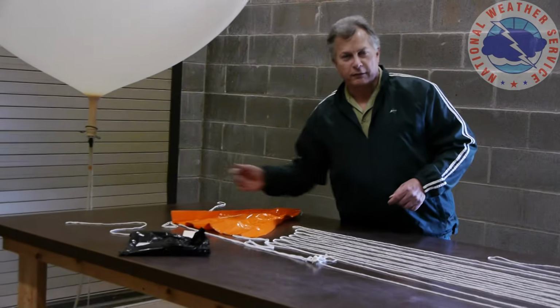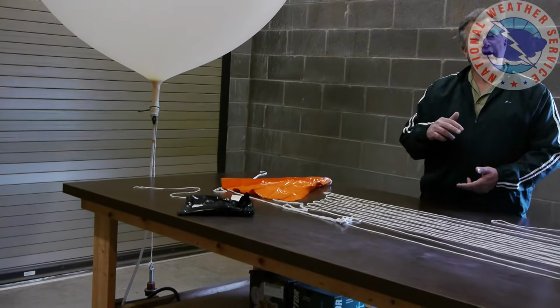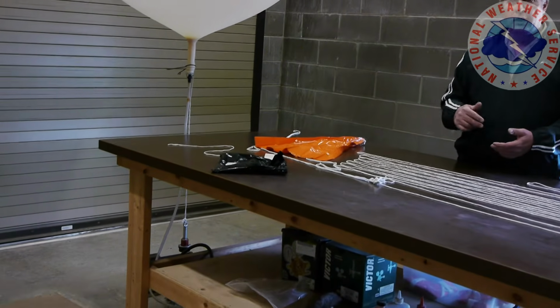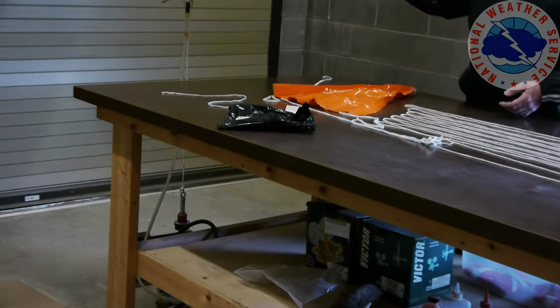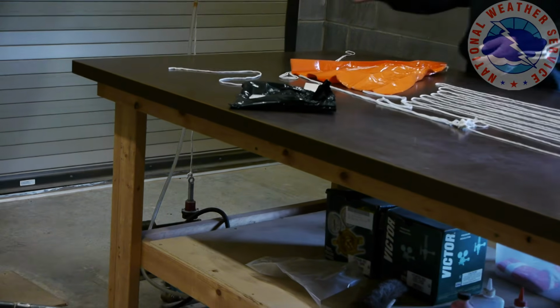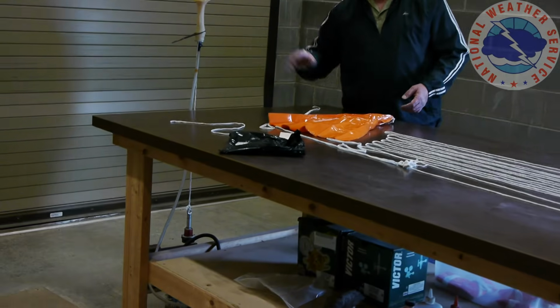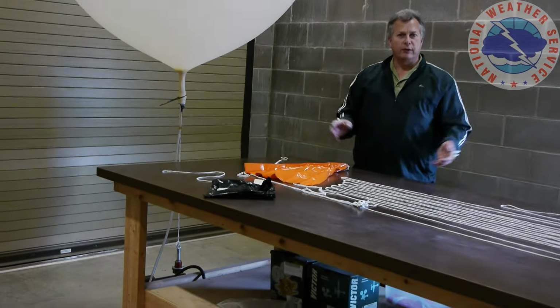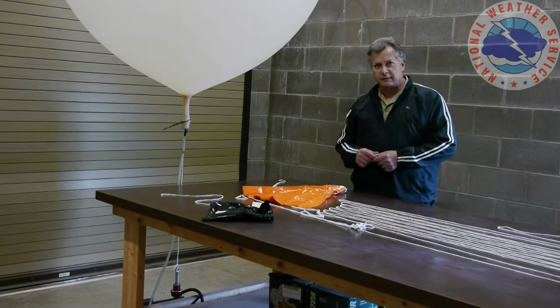Now, the balloon is actually tied off to an inflation nozzle. On the opposite end, down on the floor, is a counterweight, a combination counterweight and switch, so that when the balloon has the 1,700 grams of helium in it, it will actually lift the mechanism and cut off the gas. And at that point, I know the inflation process is complete.